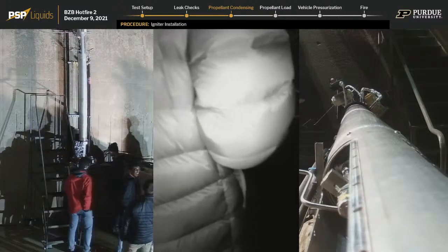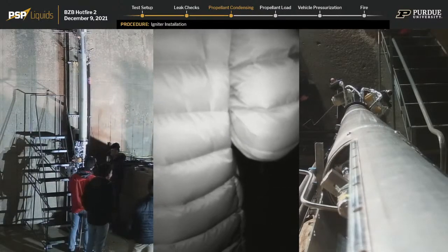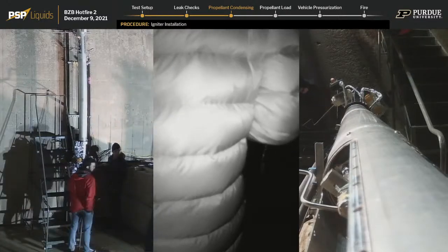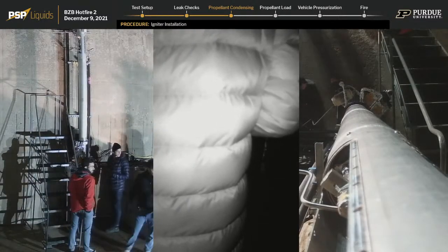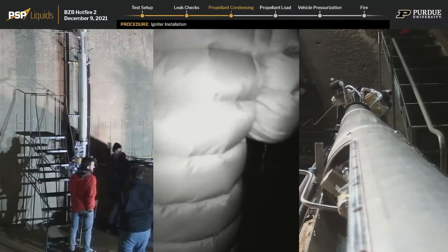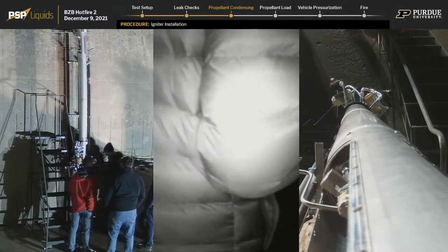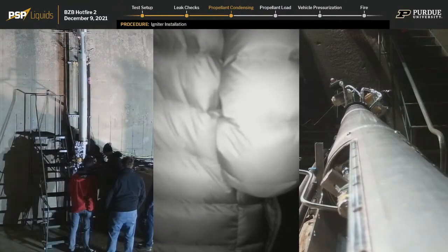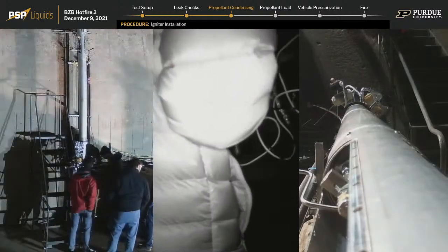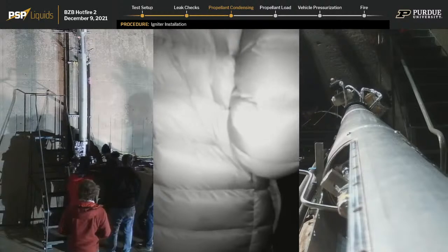Copy all. And yes, we are getting the book names in the chat now, from a variety of sources all around. Verify the igniter Wago blocks read 24 volts DC using a multimeter. So what we're doing right now is we're just verifying that all of our systems are go, and making sure everything goes okay.